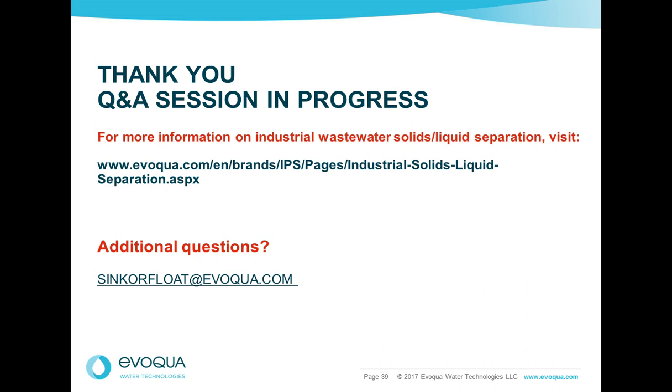Actually, both. Adequate pH adjustment is required for good flocculation downstream. If the pH is out of balance relative to the coagulant being used and the flocculant, flocculation will be impeded. So it is critical, and equalization is critical also because it is not just for flow equalization, it's also for contaminant loading, which also can affect the chemical dosing. So I would say they're both equally important.